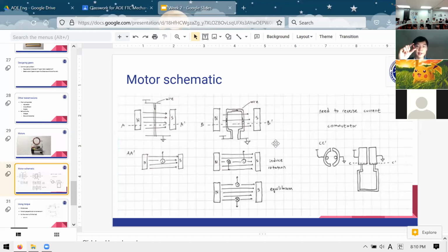Just given a live wire loop and a magnetic field, we can get any loop to align in a specific direction due to the forces involved. And all we need to do is find some way to make it keep doing that, make it go a bit farther, then align the other way, then go a bit farther, then align the next way. And one way that we do that in terms of DC motors is we have something called a split ring commutator. And it's a big word. All it means is that it allows you to switch the direction of current in the wire.